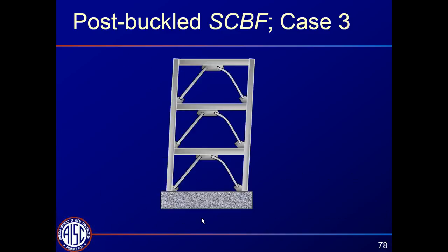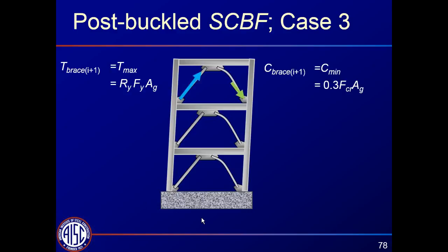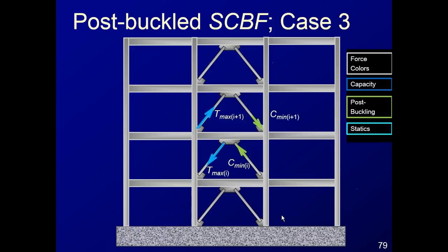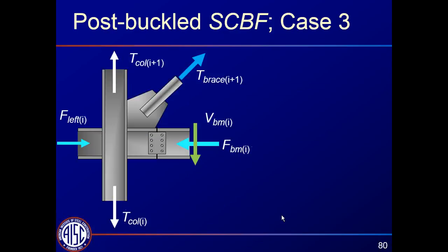When we have this stacked chevron configuration, we do the same thing, and we also determine that there has to be a high compression force here in this region of the beam. So in this case, we do the same sort of statics. Maybe the statics gets a little bit easier because there's no brace below, but you can see this force in the beam now has to be even greater to counteract what's going on there. Plus, as we all know, there's shear in the beam from that unbalanced force that has to be accommodated in this connection.